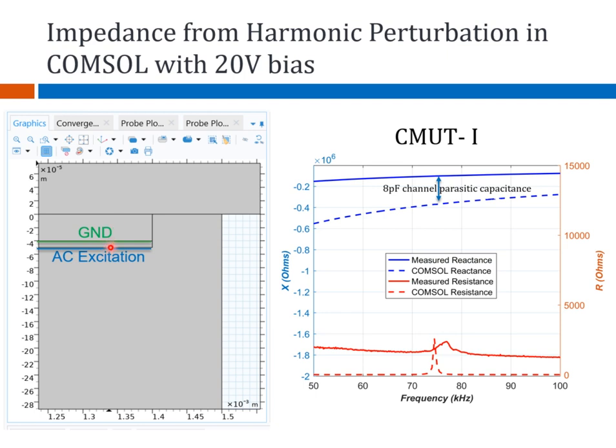and it starts vibrating, then you can see in COMSOL that it does predict the frequency around 75 kilohertz, which is correct, which is what we measure. But what we don't have in simulations is that elevated baseline, first of all, which is representative of the vibrational damping. And we also have a lower measured Q, but in the simulation, we have a higher Q.